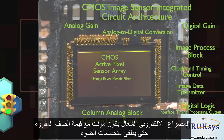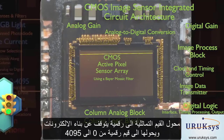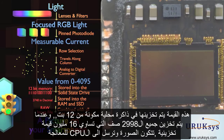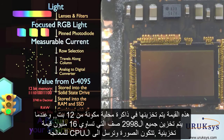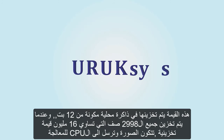A rolling electronic shutter is timed with the row value reading in order to turn off the sensor's sensitivity to light. The analog to digital converter interprets the buildup of electrons and converts it into a digital value from 0 to 4096. This value gets stored in a 12-bit memory location. Once all 2,998 rows, totaling 16 million values get stored, the overall image gets sent to the CPU for processing.